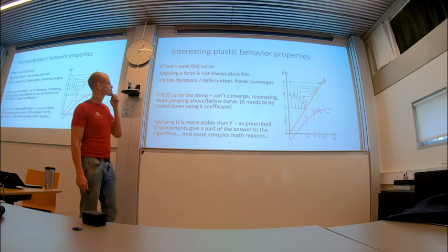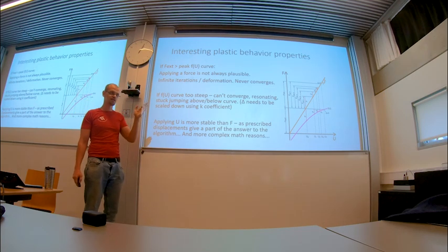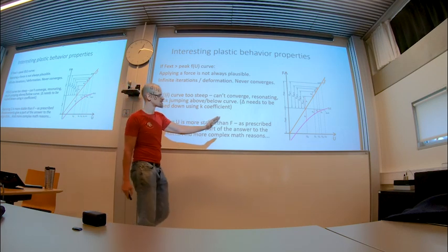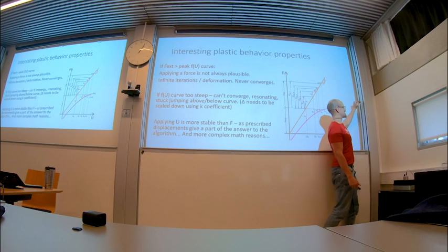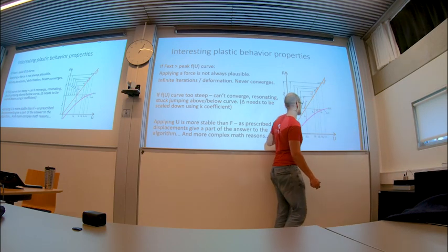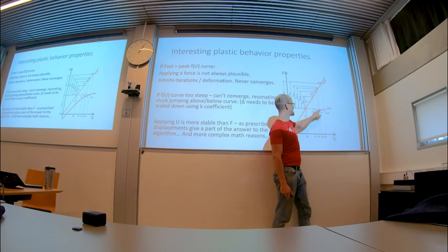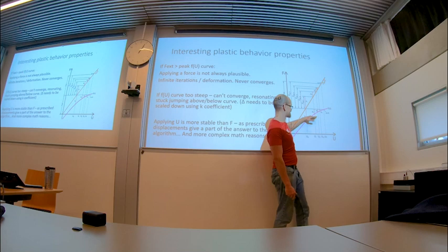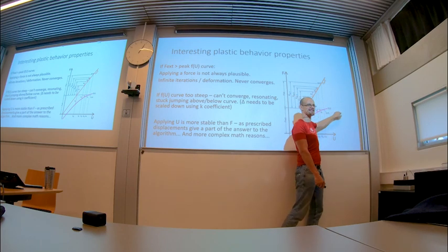Yeah, I have prepared you an exercise where you can choose many different curves. You can use the log normal. If the curve is flat like this, you will wait a long time for it to converge, because it will get into a zone where the distance from the elastic plus plastic corrector, the distance from the line, is very small, and the curve keeps going. So you're just gonna spend half the day incrementing across it.